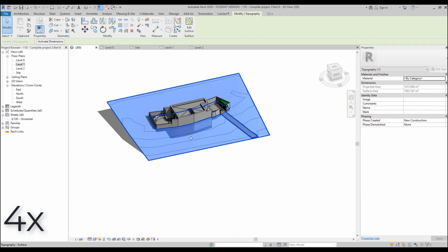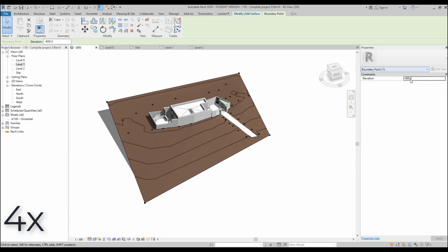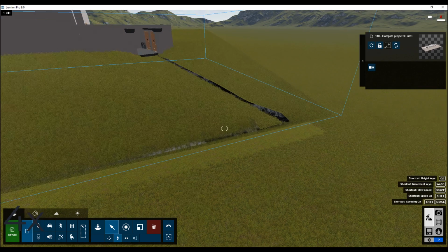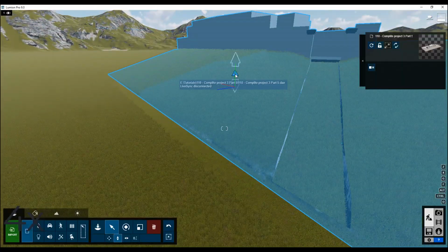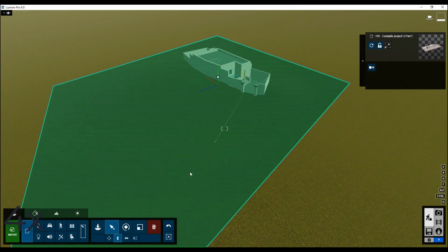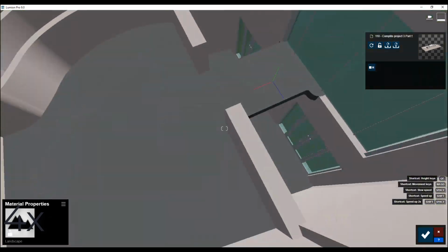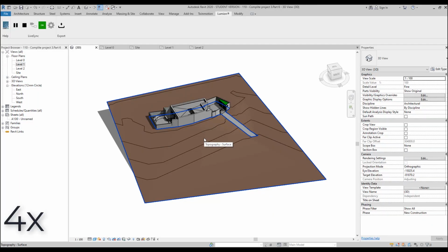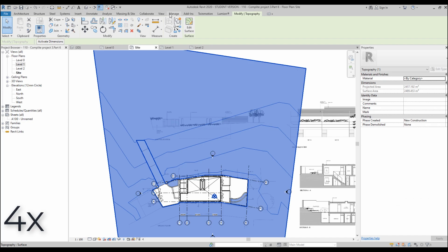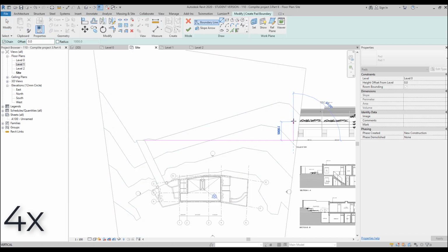Let's get some points. So now I'm just making my Toposurface a bit bigger, and I'm reloading my model. Again, I'm applying my material, and as you can see, we get a closer and closer result. So now I will draw the main road.